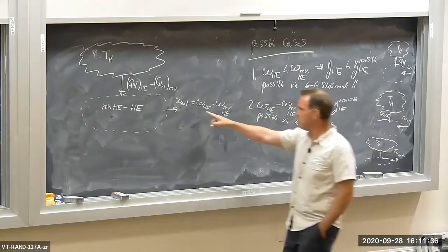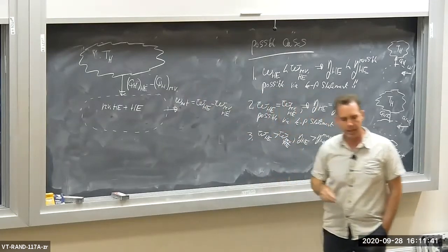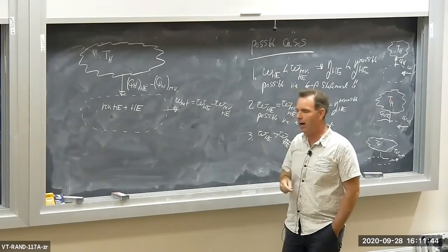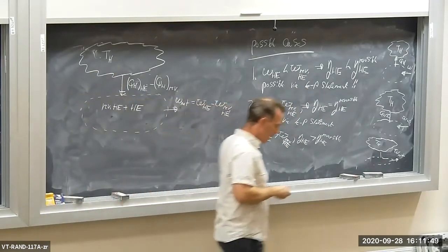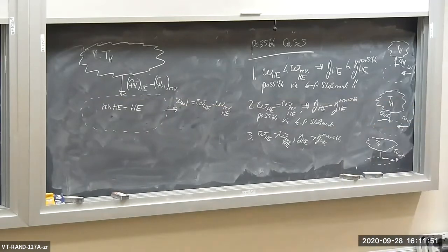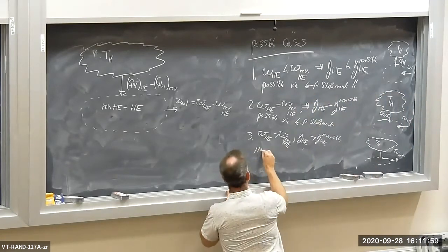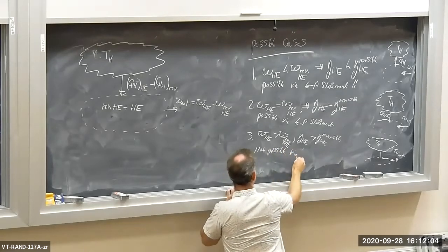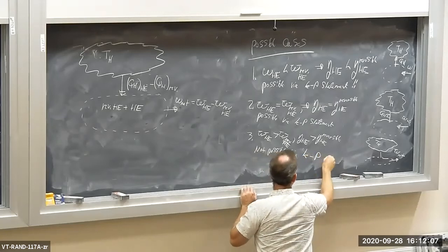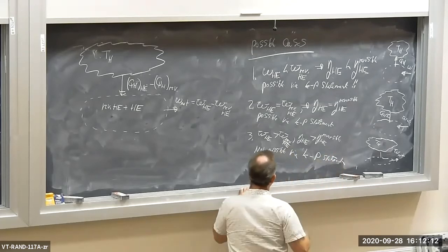W over the cycle for the heat engine is greater than the work for the reversible heat engine. Therefore, the net work is positive. Therefore, this guy interacts with a single reservoir and produces net work. That is a violation of the Kelvin-Planck statement of the second law. Not possible via KP statement. Not possible.